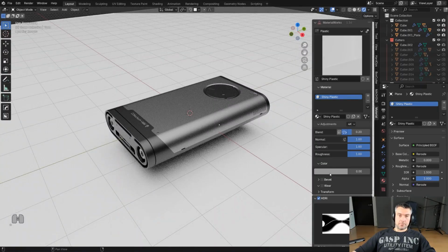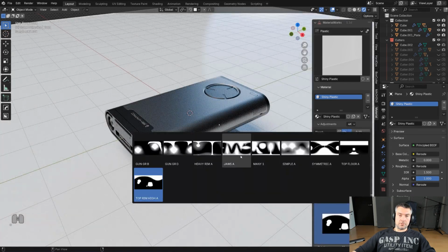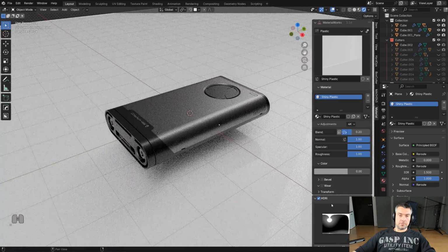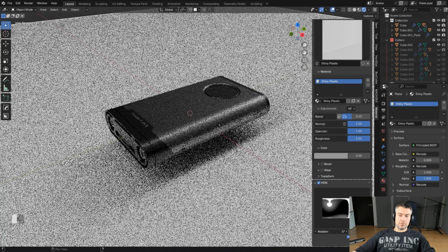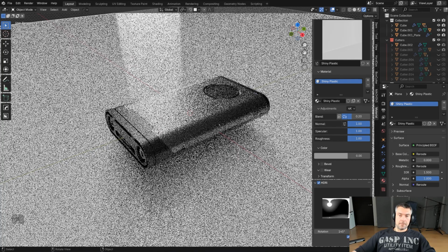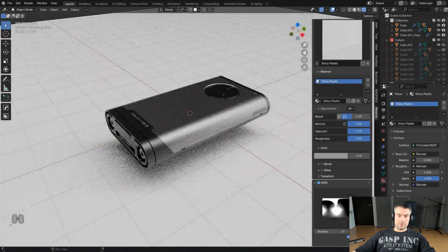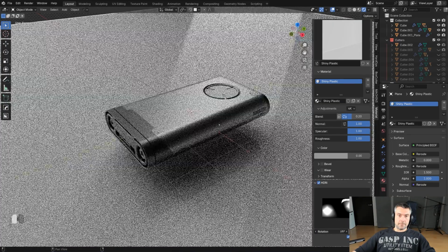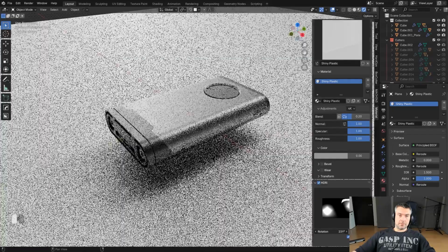And then we need to find some proper HDRI that's gonna actually fit what we want to do here. Six of these HDRIs actually come with the add-on, so you're gonna be getting these if you get that. We can obviously rotate this here, so you don't have to go to nodes at all. You can do this from this interface here. Maybe that's not what I want. Let me see. Gradients. This is an interesting lighting. Maybe something like this.